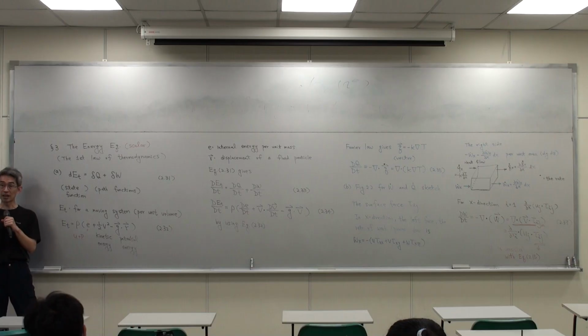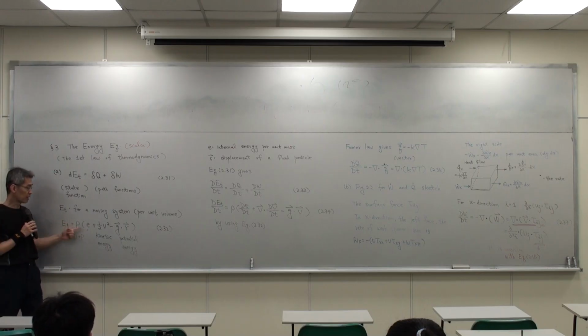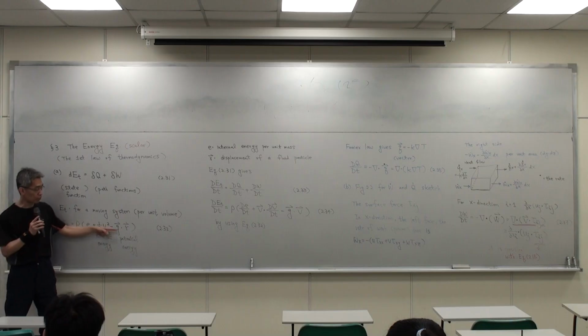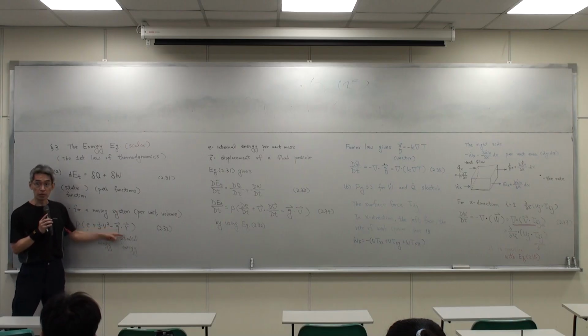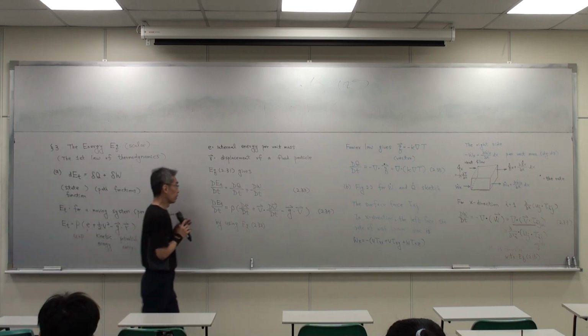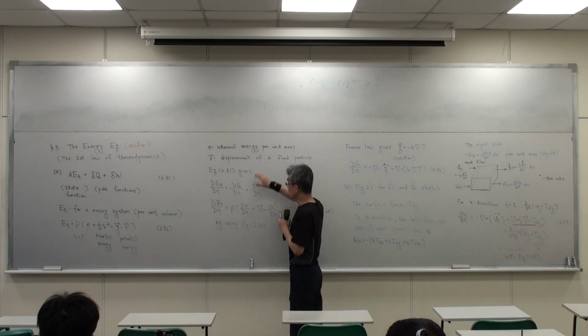So similar to the Bernoulli equation, if you only have a force. Later on we will show that if you only have a force, this equation will become the Bernoulli equation, because this term doesn't apply when you don't have a temperature difference. Pressure plus kinetic energy plus potential energy, same as the Bernoulli equation, the total energy. Then if we consider separately